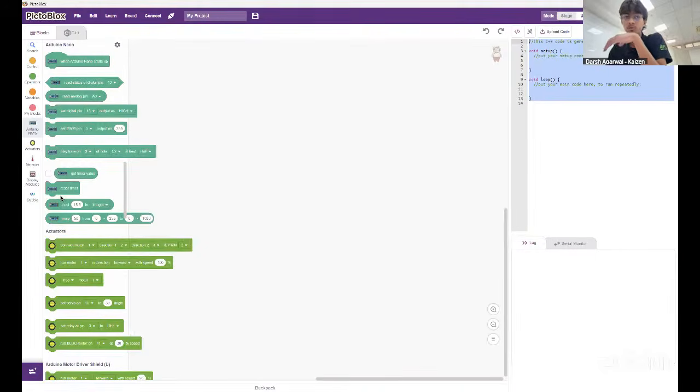So how this is going to work is that when you're wiring up your Arduino, we have multiple pins through which you can send a high or low signal, which is basically the equivalent of 0 and 1. And in the specific type of pin, which we call the PWM pin, you send values from 0 to 255, which basically acts as your decimal values between 0 and 1, so that you can set the level of power you want to add.